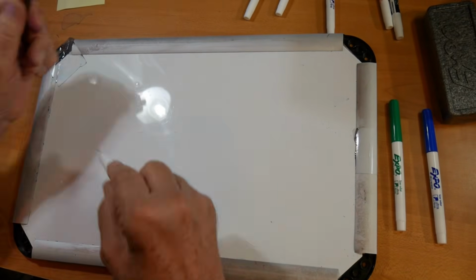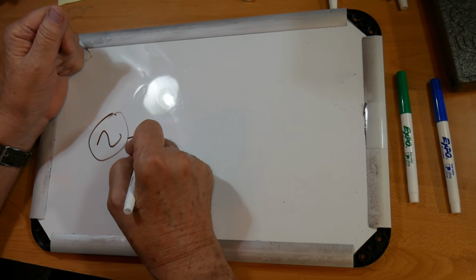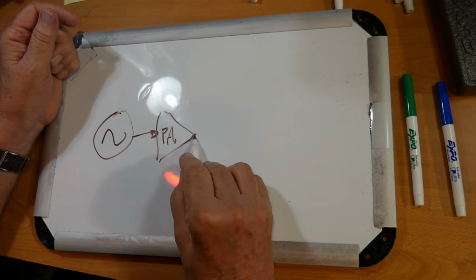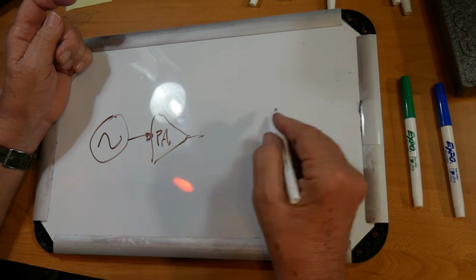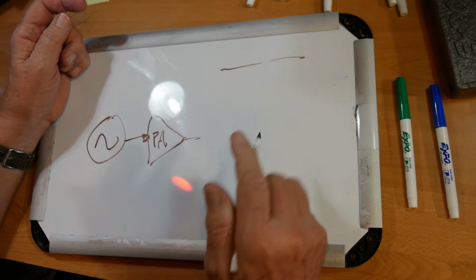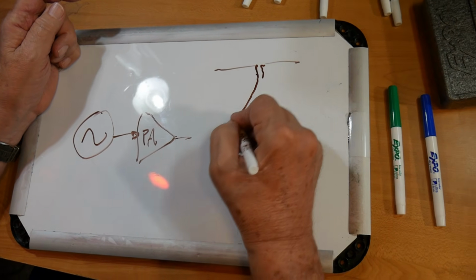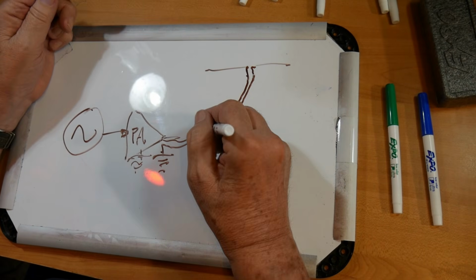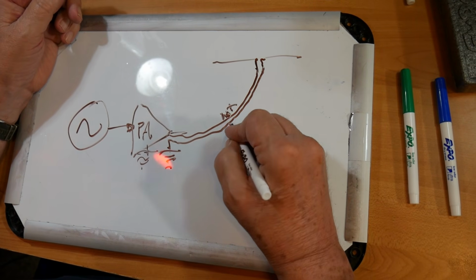Now let's look at a radio frequency transmitter. It has an oscillator, okay? And then a power amplifier. A power amplifier, and this could be 5 watts out, 100 watts out, 1.5 kilowatts out, whatever. But let's take a dipole, okay? Now the dipole, classic dipole, is joined in the middle, and this is your transmission line, okay? And this is also grounded. So this right here is the equivalent of the hot, if you will, and this is the equivalent of the return.